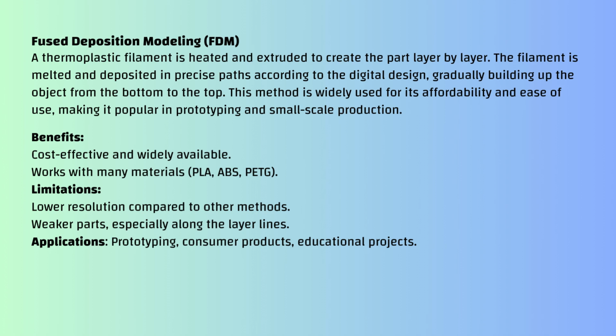FDM is affordable, user-friendly, and ideal for prototyping, educational purposes, and even functional parts when paired with strong materials like polycarbonate or nylon. However, it does come with limitations, such as visible layer lines, lower resolution, and weaker bonding between layers, which can lead to reduced strength along the Z-axis.